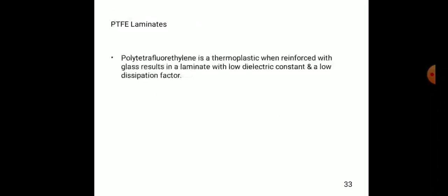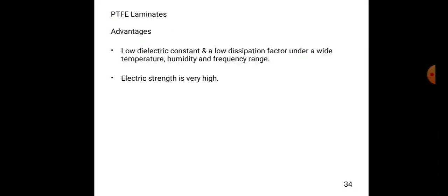Another one, PTFE laminates. Polytetrafluoroethylene is a thermoplastic which, when reinforced with glass, results in a laminate with low dielectric constant and a low dissipation factor. This is one type of laminates, PTFE, that is the polytetrafluoroethylene laminates. So the advantages of these laminates are